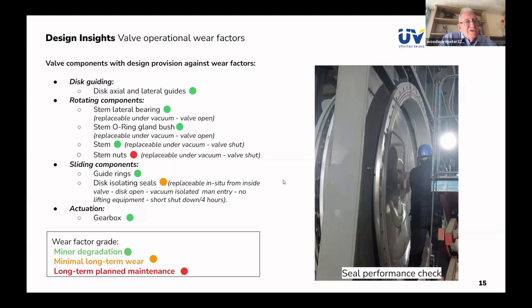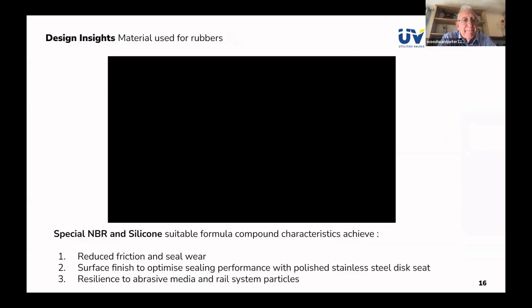And then stem nuts, they will require replacing at very long intervals, but it can be planned maintenance, and it's a very quick change. And if we turn to hydraulic actuation later with horizontally mounted valves that you might want to operate more quickly, or they can still be electrically actuated, then we can forget about the stem nut. Then it will be a cylinder and piston rod. Okay.